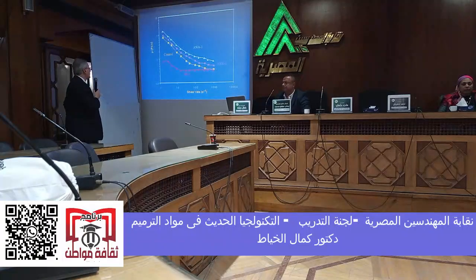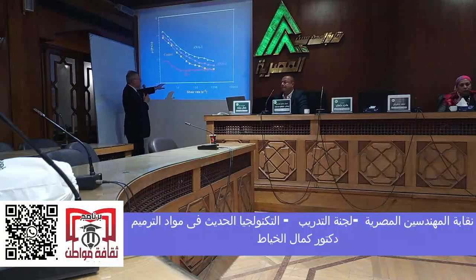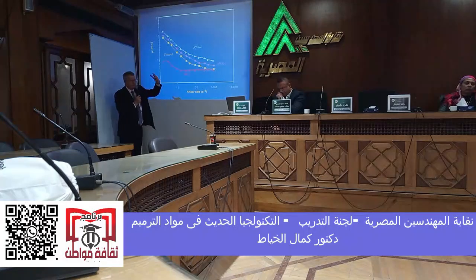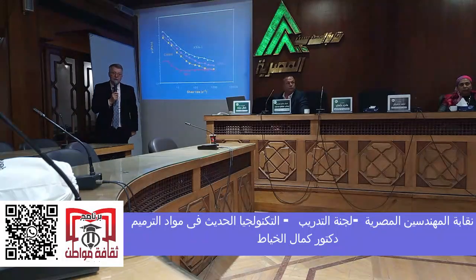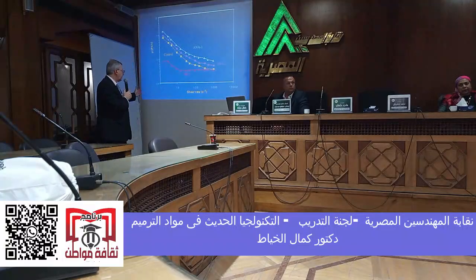But what was really good is that the microfine cement, which is red, is almost Newtonian. With the cement, in the top 3 figures, you see that the viscosity is high at low shear rates. That means with injection, initially there's a high shear rate and velocity is very high.